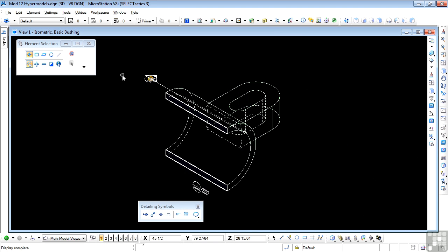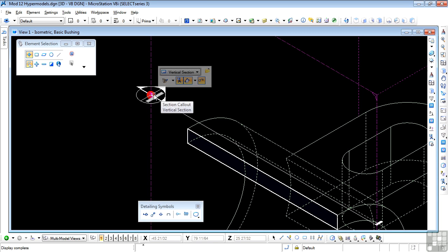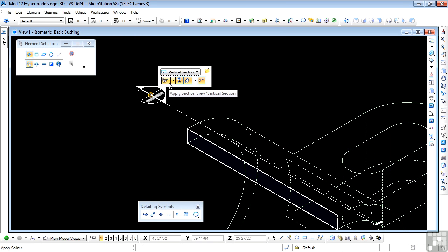So this is actually quite a nice way to display a section if you want to illustrate a section rather than a production drawing. Let's try this marker and zip into its mini toolbar. And you'll notice that there's quite a lot more information. Still called vertical section, which is where we are. This opens the target again. This one turns on or off the sheet annotations. In other words, if we'd made notes or dimensions on the sheet that we just came from, we could turn those on or off in this section.